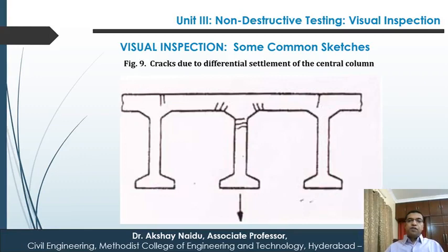Then cracks due to differential settlements of the central column. So central column is settling. So there will be differential settlement, and bending moments will be developed. There will be shear cracks here, and there will be bending cracks at the top.